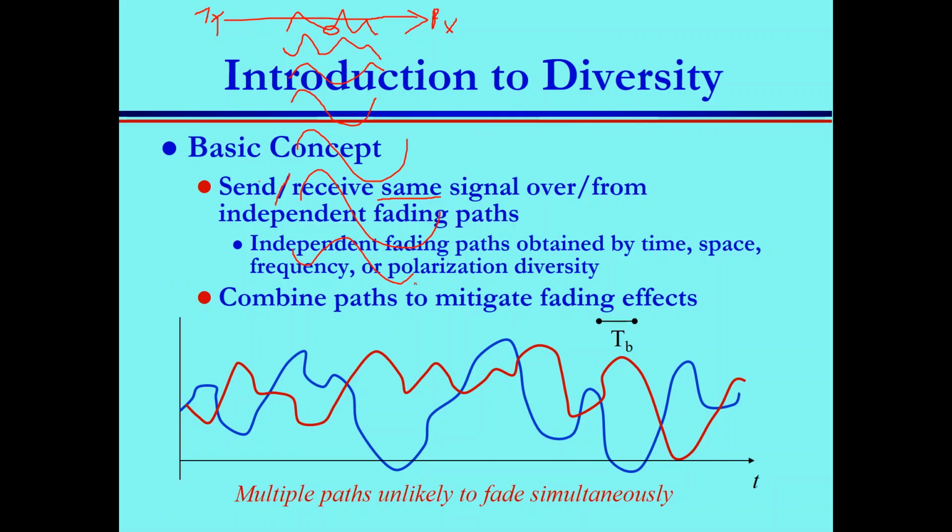This is massive MIMO. In massive MIMO, you send the signal from different antennas, the same signal, or you receive your signal from different antennas. When you combine them, since you have more than 20 paths like this, imagine, keep putting 20, what's the probability of having an error in this? 1 in 200 almost. I mean, the probability of making an error is so little. Instead of being 1 to half, to third, to quarter, to 1/5, to 1/6, it's 1 in 200. So this means that the more paths, but of course there is a trade-off. This comes at the expense of something.